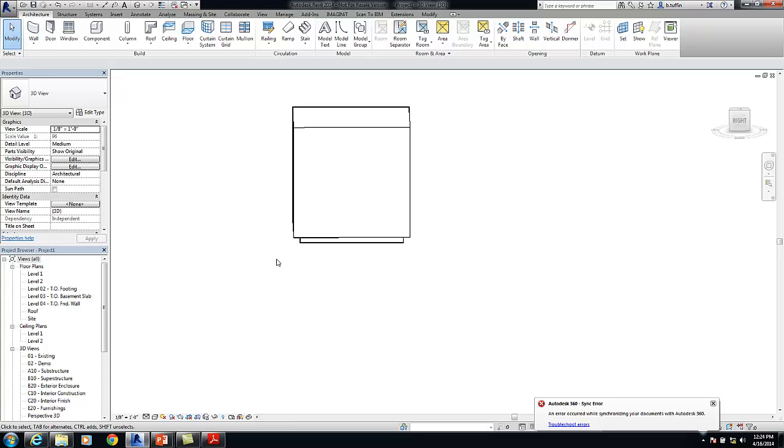We might also want to take a look at rounding the corners. That'd be a little bit more accurate representation. Now, if we're putting a radius in, we have to do that inside of the sketch mode of the extrusion. Radiuses are the one thing that we don't really tie to reference planes. We actually have them inside of the sketch mode.